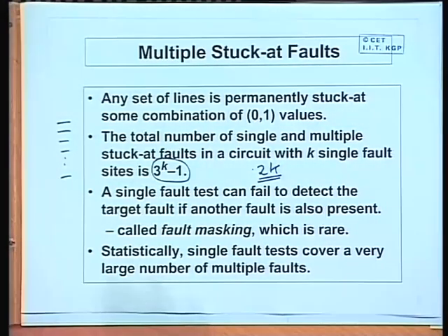Now, as I had mentioned, a test set which can detect single stuck at faults only can also detect a very large percentage of multiple stuck at faults. So, people usually do not consider multiple stuck at faults. Moreover, multiple stuck at faults have some problems which also need to be addressed, like one such problem called fault masking.